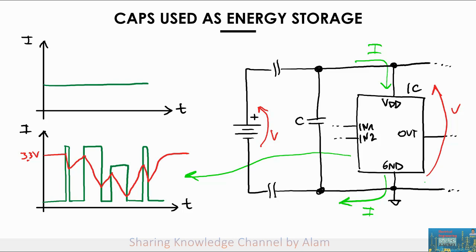And so the voltage supply can provide the charge required to bring the voltage at the integrated circuit back to the nominal value. With a bypass capacitor, the impact on the voltage is much smaller. It's probably going to look something like this. So when an extra current is required, you are going to be hit, but the amount of voltage drop is going to be much smaller, and then the system will recover. Here it will be hit again, and the release will look like that.